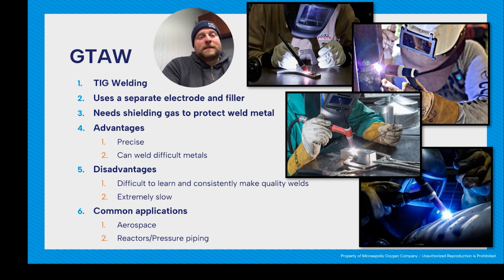GTAW, very similar as far as the naming convention. GTAW is gas tungsten arc welding. TIG is tungsten inert gas. Same reason, we could have active gases involved, which makes TIG not an accurate name. We're using a separate electrode and filler in this case.